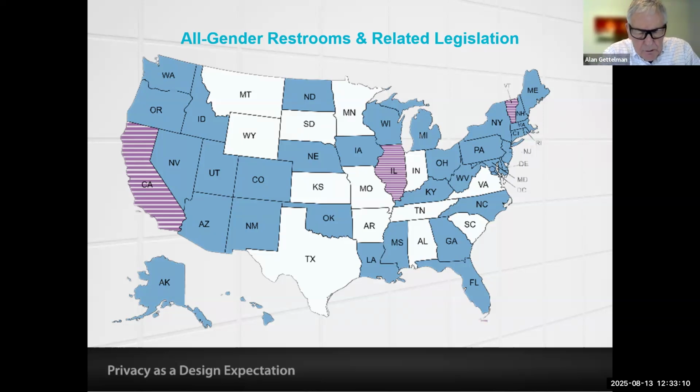You just don't attach it to the ceiling tiles or the exposed ceiling fascia. You have to provide steel bracing above the ceiling tiles to attach anything to the ceiling. Otherwise, the mounting at the floor is the same and the mounting at the wall is the same.